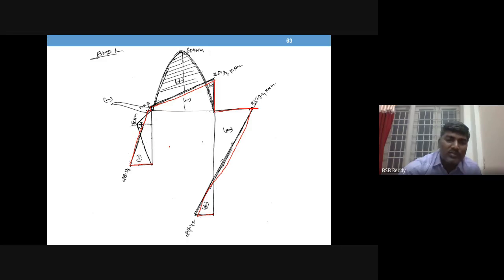And for span moments, you have a point load on AB, so take a simply supported beam and draw the BMD. Same for the UDL you have on BC, draw the BMD for the UDL, then just hatch the portion which is left over, something like this. So this is the final BMD.